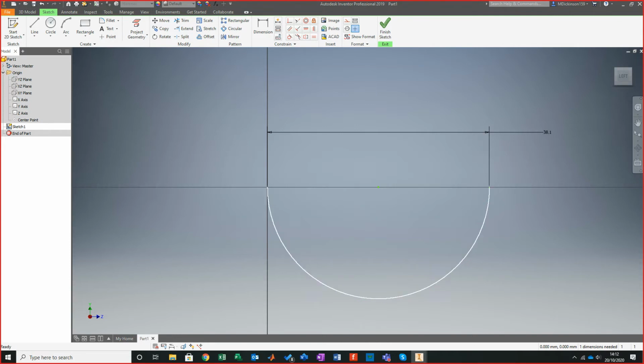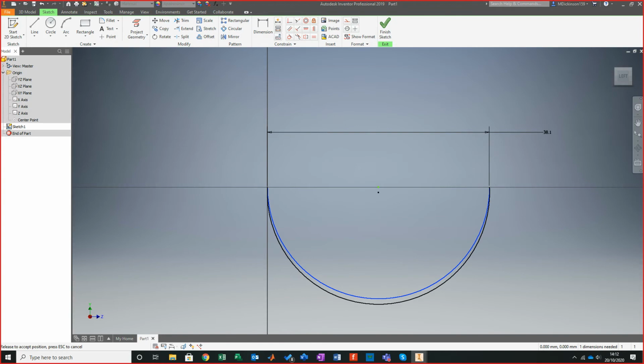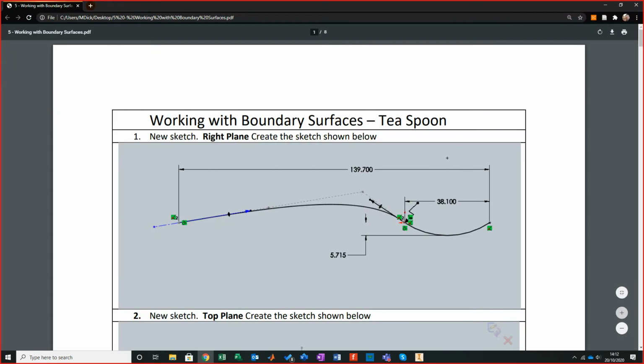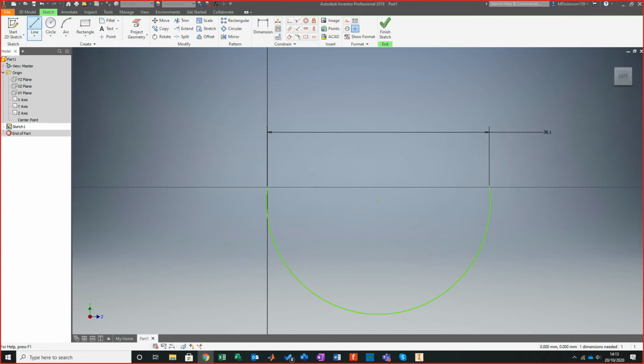And what I should be able to do is make it bigger, make it smaller, as ever, just shrink to whatever. Now what I actually want to do is recreate my arc here, my maximum measurement here. Sadly, Inventor does not contain the ability to measure outside of a minimum for an arc. If anybody does know that, please let me know. I've been racking my brain to regenerate that, and it's bugged the living god out of me.